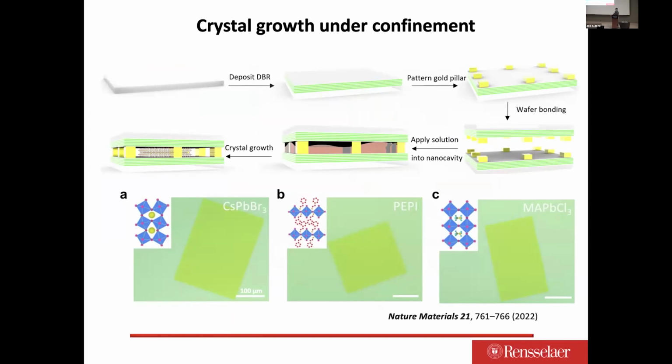So in order to improve it, we decided to use a different method, essentially slightly modifying this. We start with 6-inch wafers, make them ultra clean, and fabricate with techniques similar to those used for gravitational wave detection to make the mirror really as flat as the wafer. Then with high-quality gold, we pattern pillars over the entire 6-inch wafer with a variation of about 1%. Afterwards we do wafer-scale bonding, and eventually cut this into small chips. Across the wafer you have 1% variation, but in the center of the chip you have 0.5 to 0.2% variation. So they make the cavity as flat as an MBE sample.